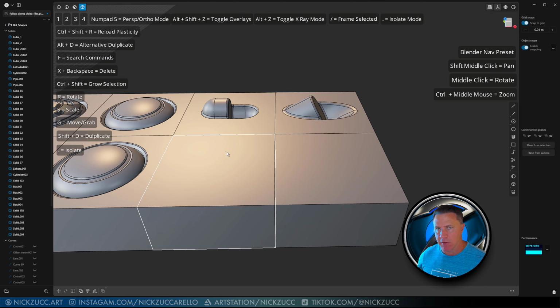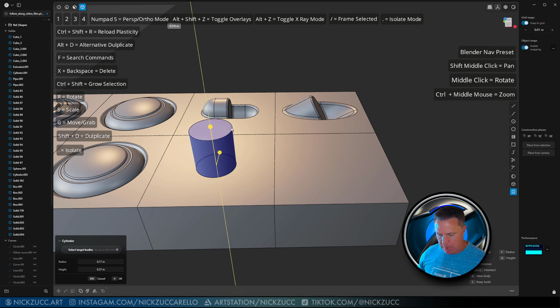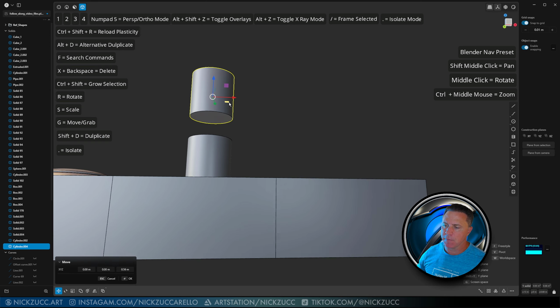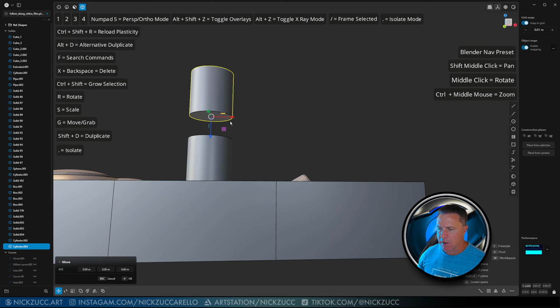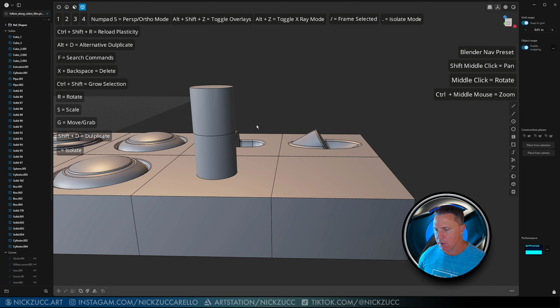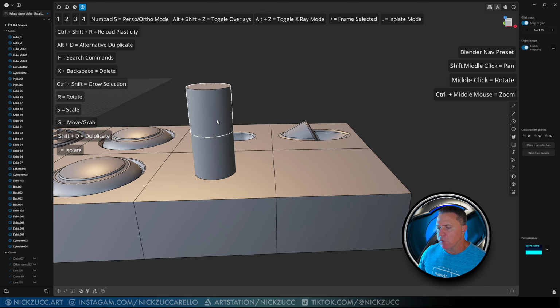The creation of the shapes themselves are not that difficult. I'll show you this. So we're just going to start off with a cylinder, and I'm going to drag up from the center here like this. Just click and drag up. I'll tap B for a new body, and I'll go ahead and make it about this size here. Right click to confirm it. I'll hit Shift D to duplicate it. I'll move this up and tap V, snap it here. And if I move down, I can hold down Control and I can snap it right there. Okay. All right. So we've got these two shapes.